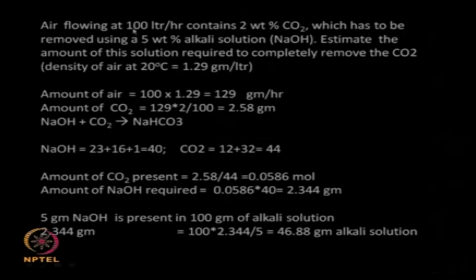Now air is flowing at 100 liters per hour, right. So I will require 46.8 grams of alkali solution per hour, because air is continuously flowing, which means carbon dioxide is also continuously flowing, and you have to continuously supply the alkali solution so that you can capture all the carbon dioxide that is present. So you will require 46.8 grams per hour of alkali solution to absorb all the carbon dioxide.